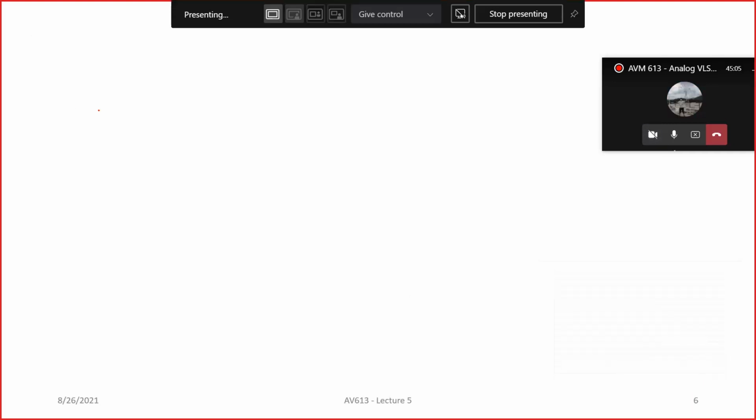What exactly is the maximum width allowed for filling in a particular metal layer? That will also determine the capacitance. So that will be set by the DRC rules, and it will differ from process to process. If I remember right, I think 40 micron length is the maximum here. Okay, I'm not sure, I have to check. I think L max of each finger is around 40 micron, and the number of fingers also will have a max number. I don't know if it's 30 or 40 or 50, something like that. Okay. So it will differ from process to process.